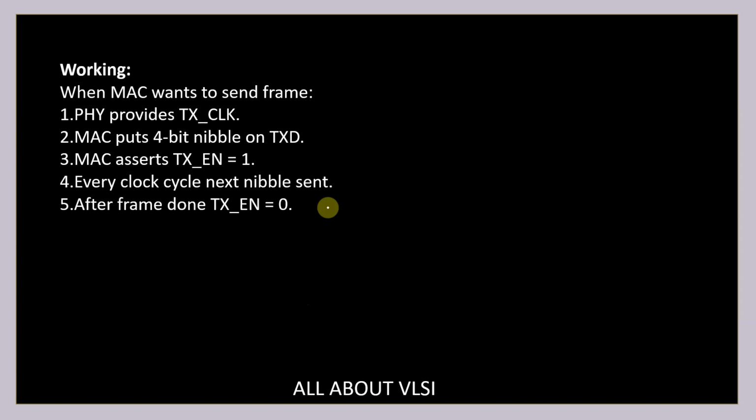So if I want to have a communication, then the physical layer is going to provide me the TX clock, then the MAC is going to put the 4-bit data onto my TXD, and the MAC is going to assert TX underscore enable equal to 1, and every clock cycle the next nibble is sent the same way, and after the frame is done, TX underscore enable is equal to 0. How exactly we are going to use TX underscore error, we will discuss in detail when we implement this in our MAC controller.